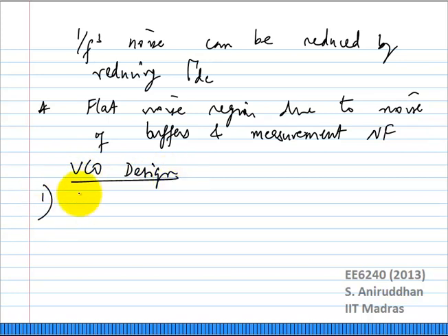So let us say oscillation frequency was some f naught. Okay, so how would you start? Yeah, so you start off with the oscillation frequency. What is the oscillation frequency? 1 over 2 pi root LC, remember that. Okay? So where would you start? How do you choose L and C?